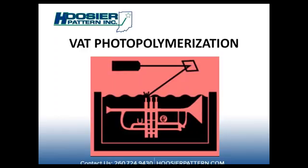SLA, which is stereolithography apparatus. DLP, digital light processing. 3SP, which is spin, scan, and selectively photocure. And the new one that's out is called CLIP, continuous liquid interface production. The vat photopolymerization process can get you a high level of dimensional accuracy and produce very complex builds. You're able to produce a part that has a very smooth finish and a relatively large build area. One of the drawbacks is all the materials for this process are UV curable photopolymer resins.